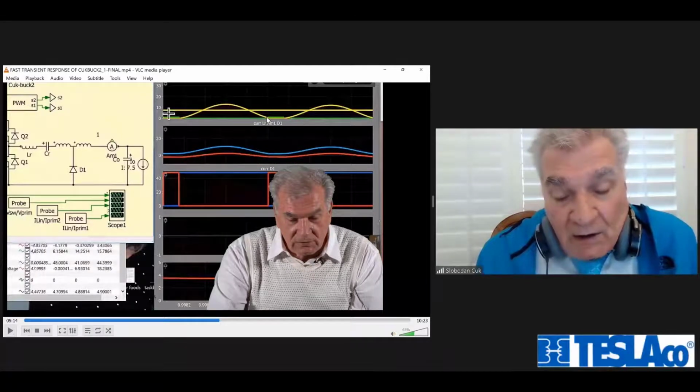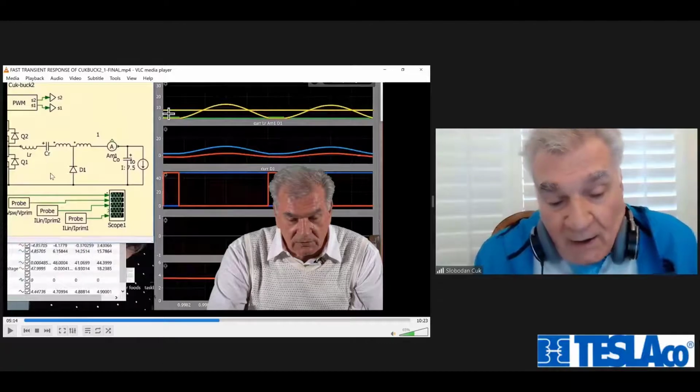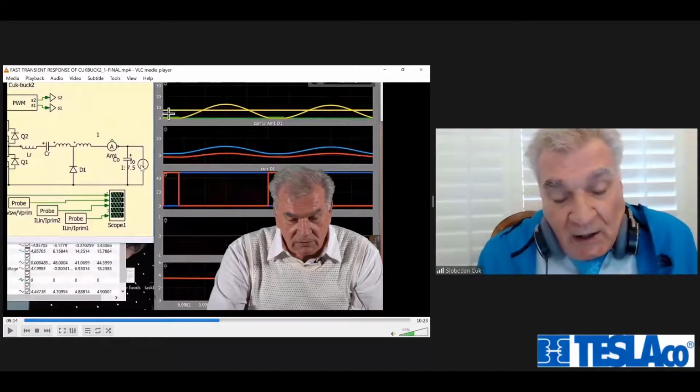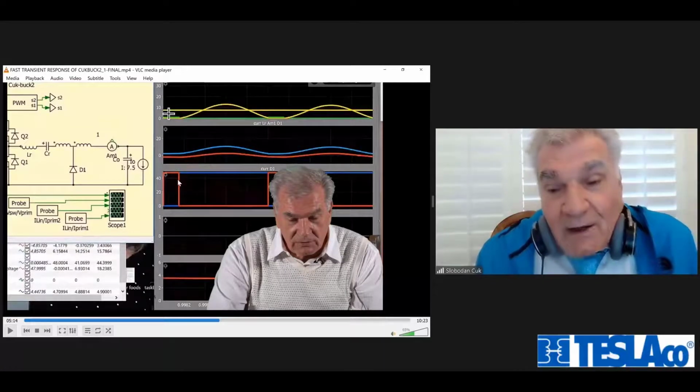And the other point is, you notice that this resonance is just half of the off-time interval. If I now make two identical converters in parallel, they will share the DC current, and one will have 7.5 amps and the other will have 7.5 amps, but what will happen? The ripple currents will be directly out of phase and cancel. Isn't that beautiful?